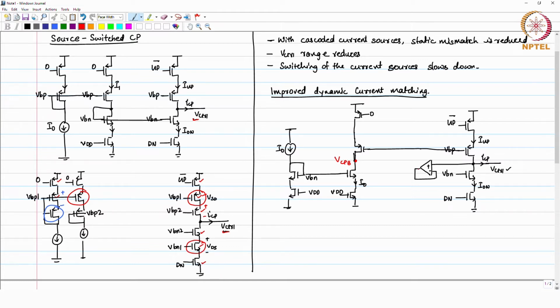So, what I need to do to force it is compare this voltage, the buffered V control voltage, with our buffered V control voltage. I take this buffered V control voltage, connect it here, and then choose the V bias voltage. Just think about it: you may bias your charge pump with V control.